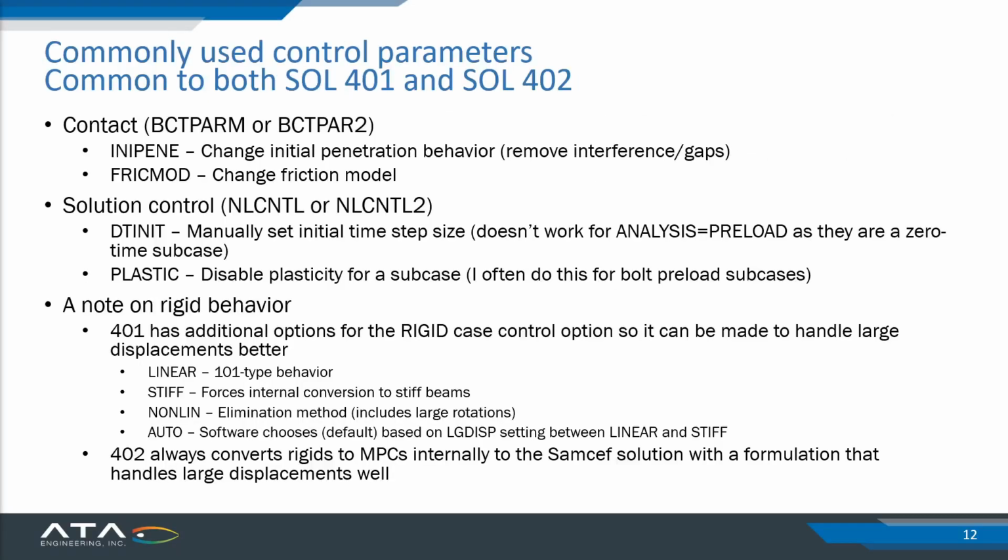To talk about some of the commonly used ones that I personally find myself using, I'm just going to go through some of the major ones, let's call it. These particular parameters are available on both the solution 401 and 402 versions of either the nonlinear control card or the contact control card. So the first one is the INI-PNE flag, and that's the initial penetration behavior flag. And that basically allows you to remove interferences or gaps in contacts before you start your solution.